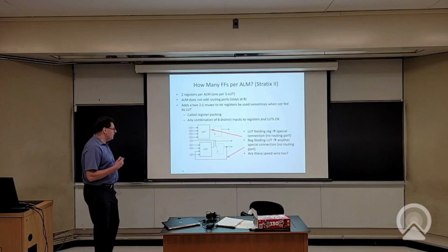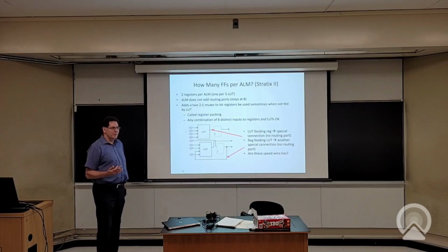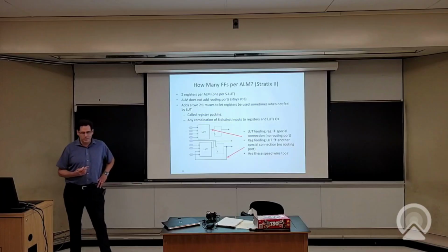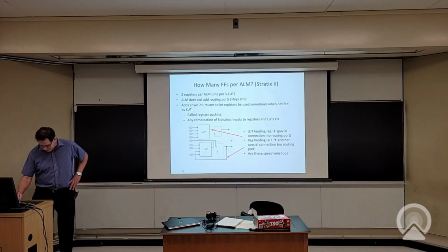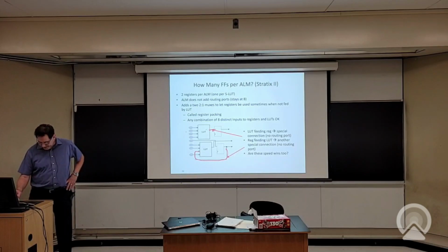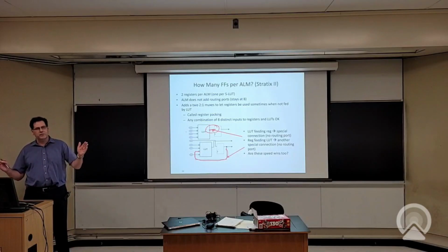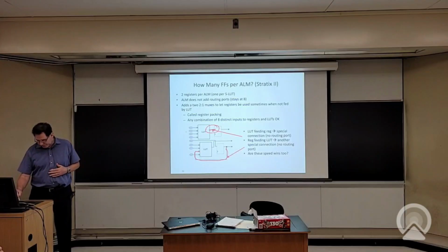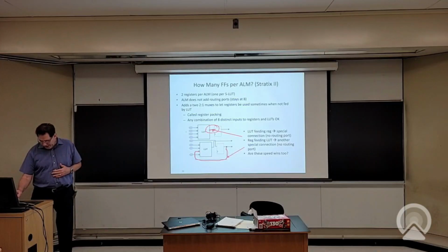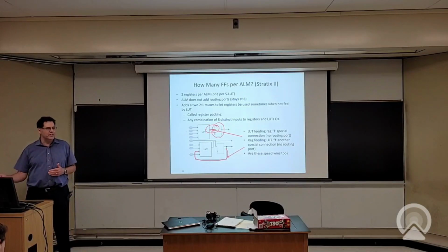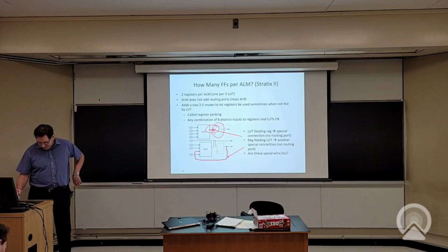So once we saw this, we figured out why it happened. It was kind of interesting that all of us had the wrong intuition. This connection is much faster, so you think it should speed things up just like this one did. This connection is the end of a timing path. All timing paths start at a register and end at a register. So for sure, any critical path that was going to end at this register, we just sped up, because all paths ending at this register go through this connection.